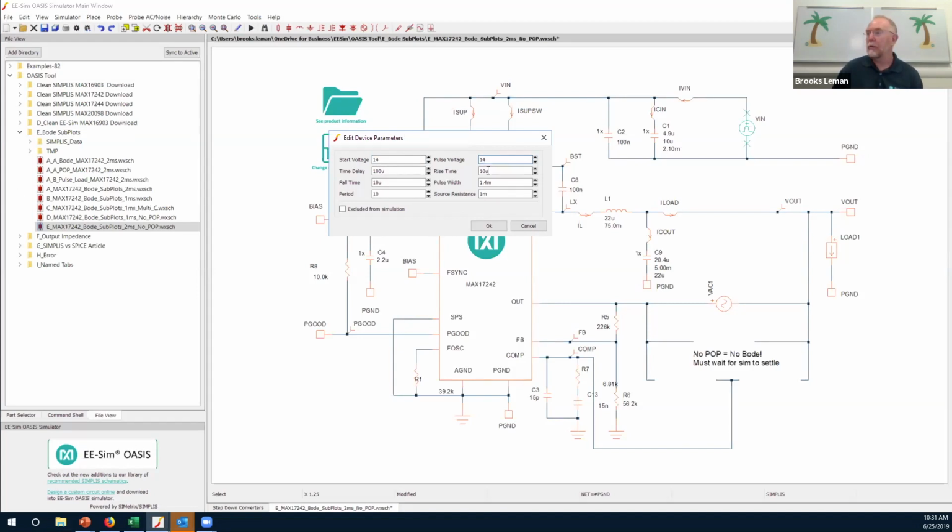Never set the rise and fall times to 0, which makes the rise and fall times so fast it could cause excessive and fictional current spikes in your simulation. It can cause your simulations to take a long time to settle, and in some cases can cause them to fail.